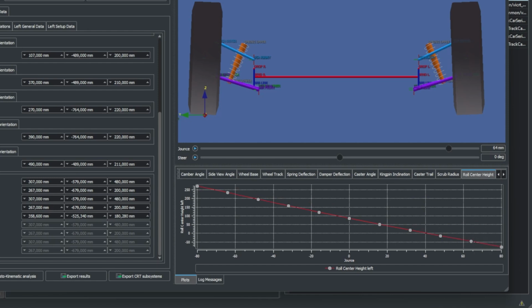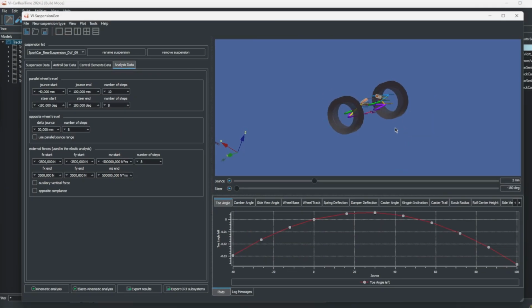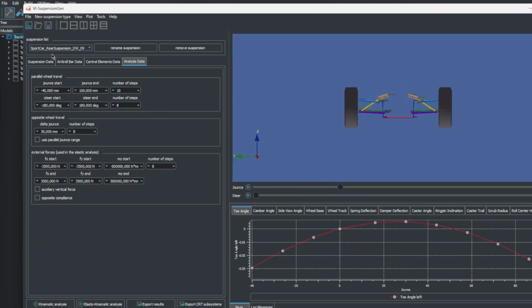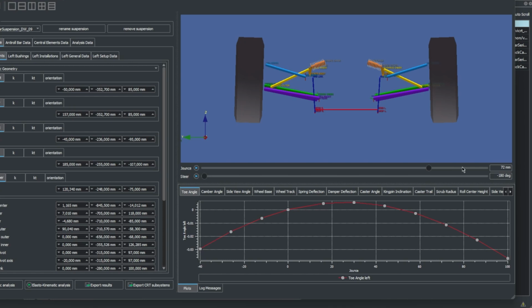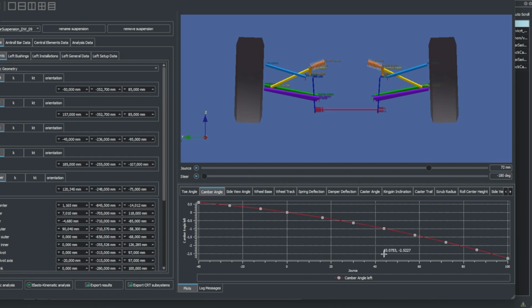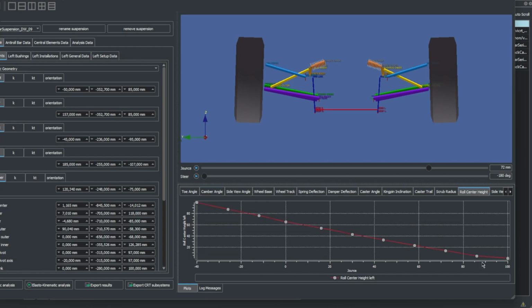Don't worry about following along this next step, but if we were to look at the rear suspension, this is what we would see. At rest, the rear suspension is lowered by around 75.5 millimeters from the design condition, where it looks like this. Here we can see a tendency towards toeing out in compression. The camber gain, once again, is at its steeper region, and the instant rear roll center is also very low, but higher than the front one.